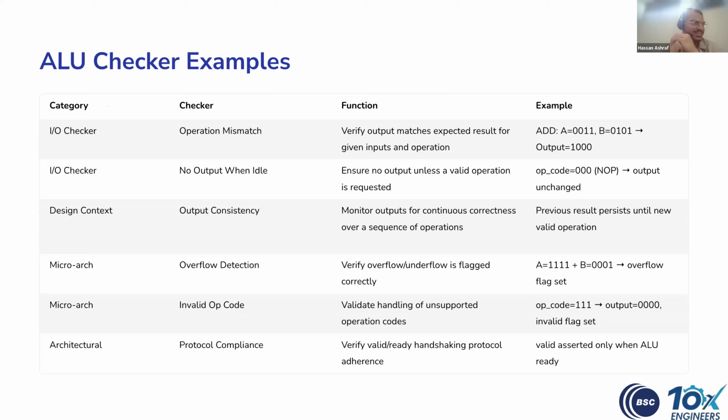Yep, you're right. And that's where white box testing is helpful. So in white box, you can see the assumptions in the RTL, what assumptions have been used by the design team, and you can challenge them using your checkers and stimulus in the test case. Thanks, Hassan.